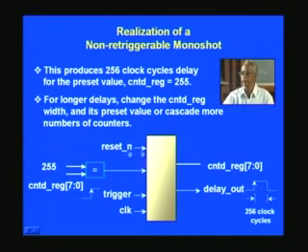And once again you have a synchronous reset, and now this time I have put D, because what all we have learnt, we are going to put together in a single program and then execute. So if you just give the same name, it will be overwritten. So I am deliberately putting a different name for that. So here D stands for that, and this is 8-bit, and that's a trigger applied here, and this is non-retriggerable. That means to say, once you have triggered, the delay starts. Any amount of further triggering will not really have any effect. So that's the idea here, and that's naturally a clock. And let us see how to code it.